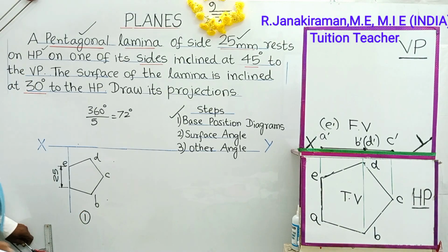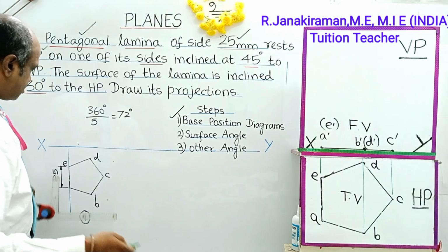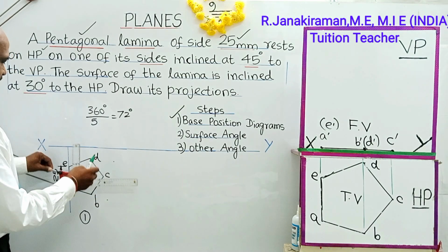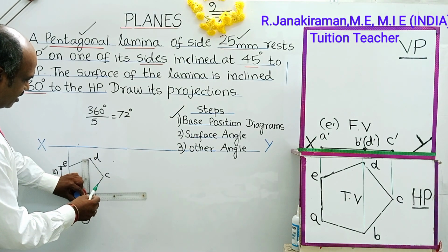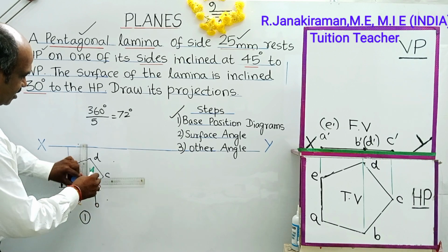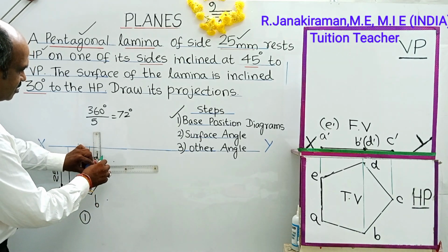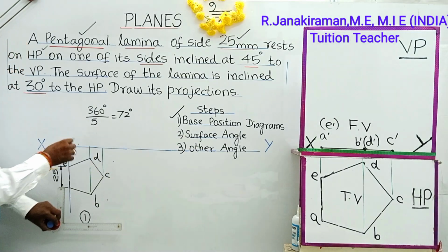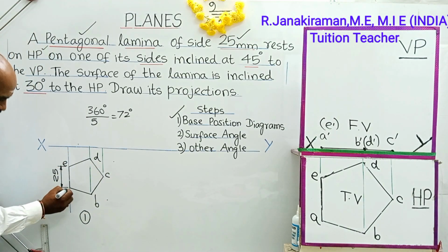Next we go for front view. Using 2H pencil, draw vertical projectors from E. If you draw a projection line from point B, it also merges with point D. Using 2H pencil, from C you draw a vertical projector. Where these lines intersect with the horizontal line, shall be marked as point A.